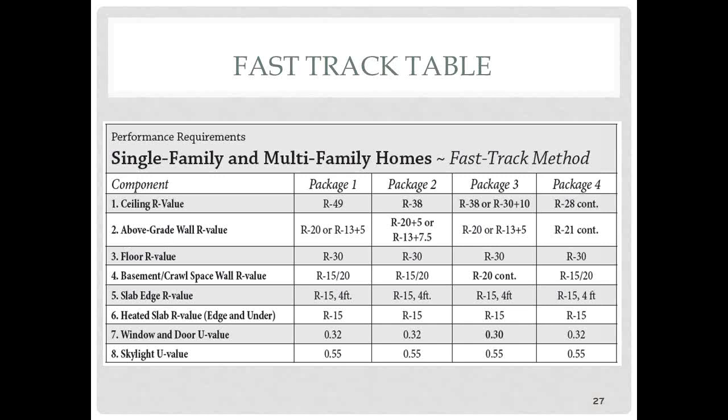Under the basement crawl space wall R value, you'll see a similar kind of confusing number there, R15/20. What that means is R15 continuous insulation or R20 cavity insulation.